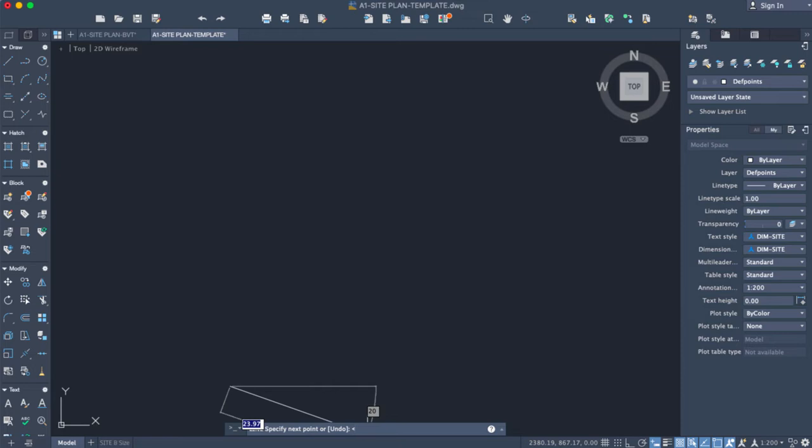So when you are typing the survey unit, just make sure you are putting the angle. If you look at the PDF file on Blackboard, it says 15 degrees, but there is no such degree sign on the keyboard, so just make sure you're typing D for degrees. It says 15 degrees, 57 minutes, 00 seconds west. Just make sure you are using the feet and inch signs for minutes and seconds. Press enter. Once you press enter, it will take it to that angle that you're trying to draw your line to.